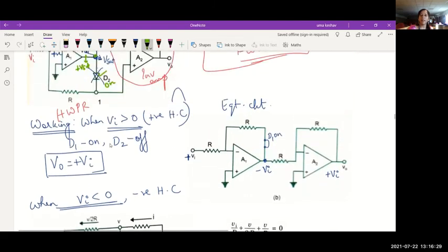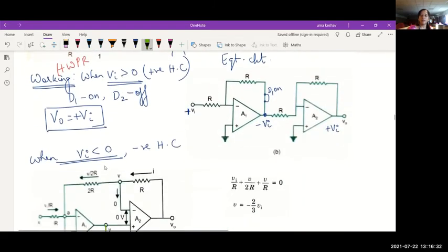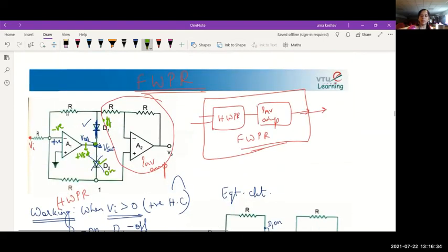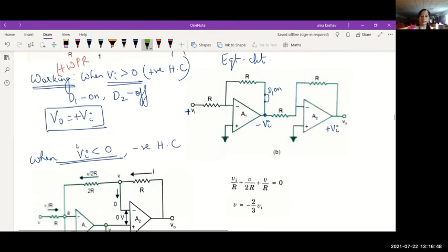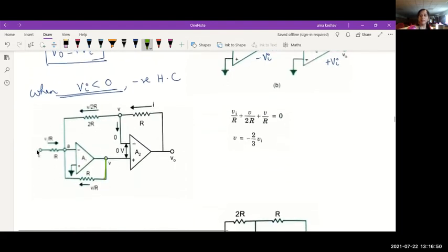Okay. And you have this resistance here. You have this R in series with this R because this connection is not there. Now, these two resistors are in series and it's equal to a value 2R. As you can see here, 2R. The input is there, Vi at this point through the resistance R, and this part is there as usual. So this would be the equivalent circuit of the op-amp.